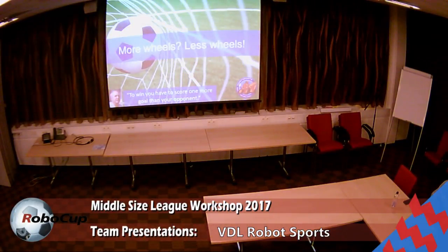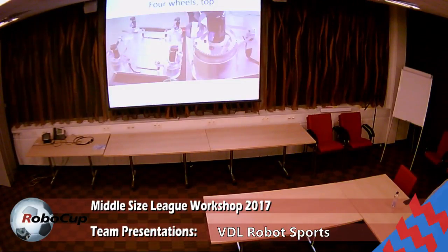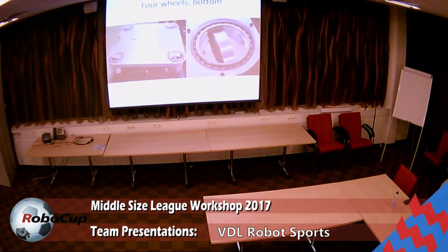One other topic I'd like to discuss. I previously discussed with Lotte briefly, and with more wheels. We think less wheels. So let's see. This is our robot in 2001. We're still in the mechanical workshop of Philips. We did not have the smart decision to put two powerful motors. We had one powerful motor for powering the wheel, and one less powerful motor for orienting the wheel. This mechanism comes back in the 8-wheel robot that Tech United is now proposing. So quasi-holonomic, it's not real holonomic.